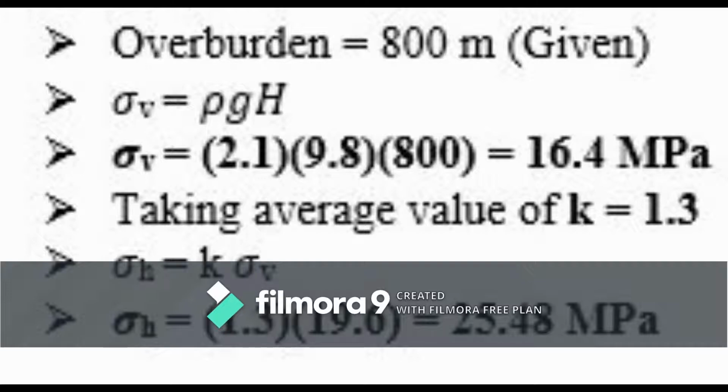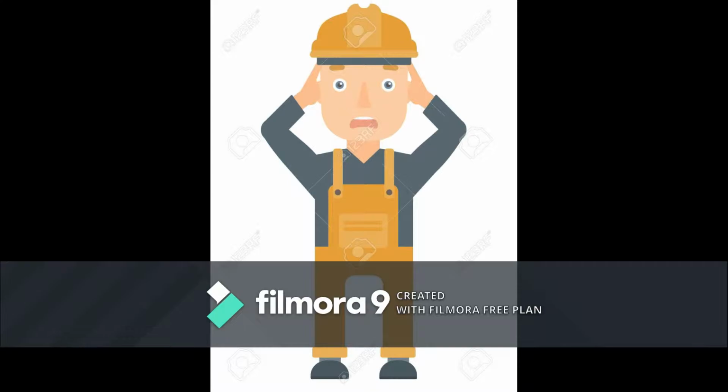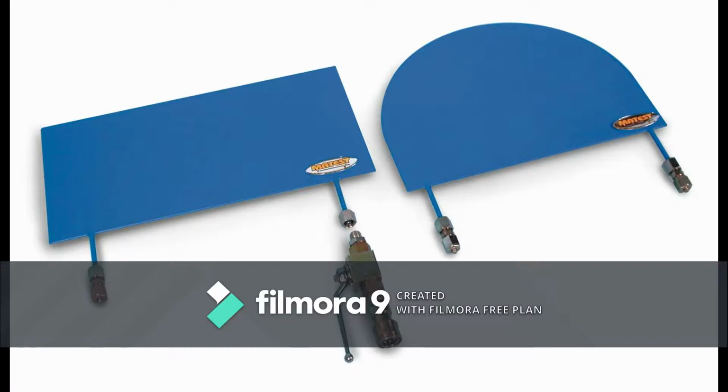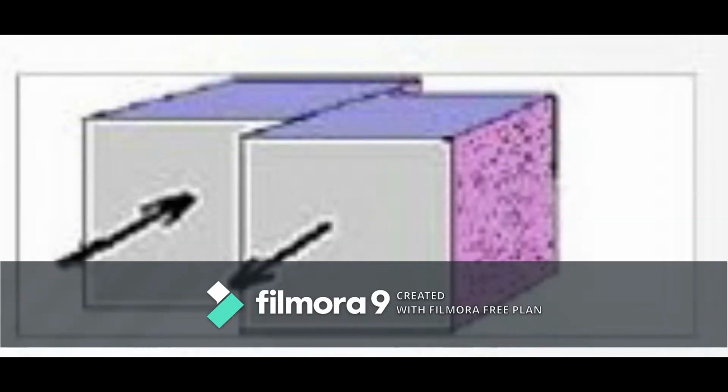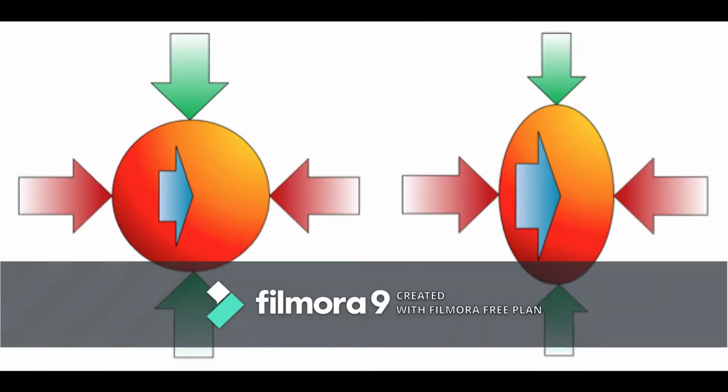In the next part, a problem arose during the engineers' work: the engineers were not able to acquire data using the flat jack. We have to give the reasons why this happened. The reason can be that the flat jack method is not able to measure the shear stresses produced, or the rock behavior is not reversible. These can be the reasons that the flat jack failed to produce results.